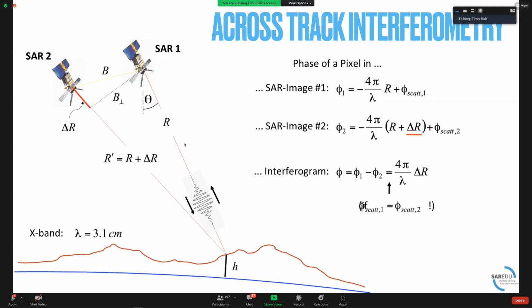Clearly, when we go into practice and are making applications, the pixel size, the size of the resolution cell, also has a very big impact on the final product that we can achieve. The resolution of your DEM is mainly a function of the pixel size.